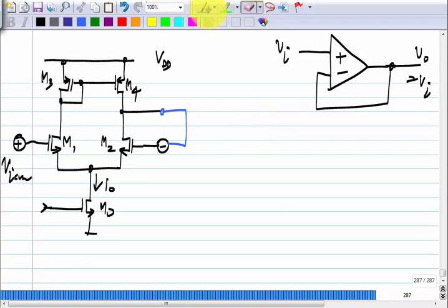Again, it is true, the op amp is providing negative feedback, and the same negative feedback action we can see here, right. So, just imagine that this was slightly more than I naught by 2 and this current was slightly less than I naught by 2. The total current is fixed, right. So, what will happen? M3 and M4 is a current mirror. So, what will be this current?